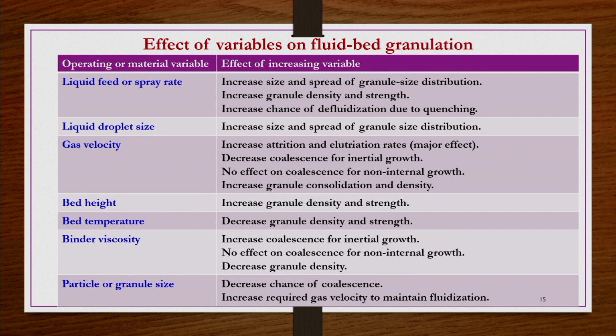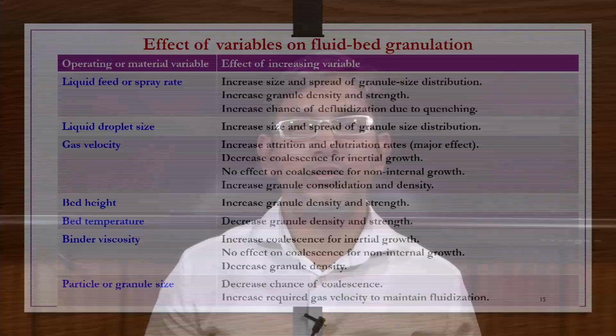If you take a higher viscosity liquid, in general you may get a bigger droplet from the same size nozzle opening compared to a low viscous liquid. That is, if you take a low viscous liquid and a high viscous liquid and pass them through a nozzle of the same size, the high viscous liquid is going to form a bigger droplet.